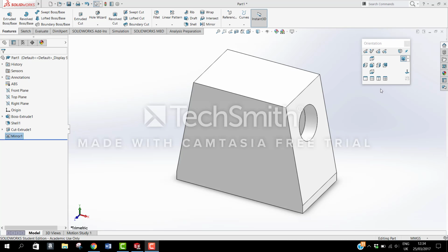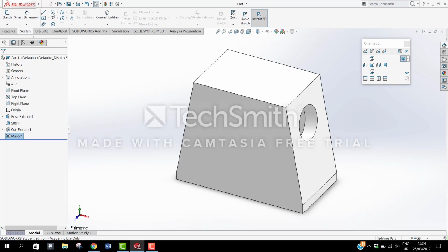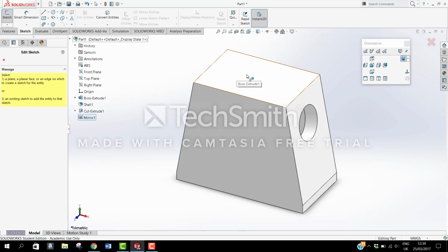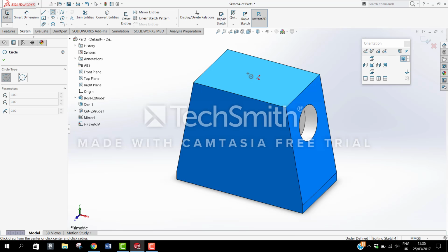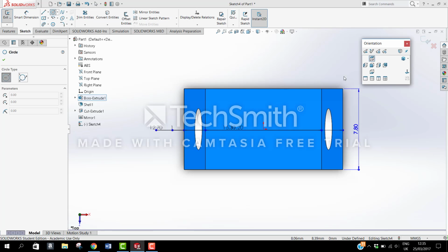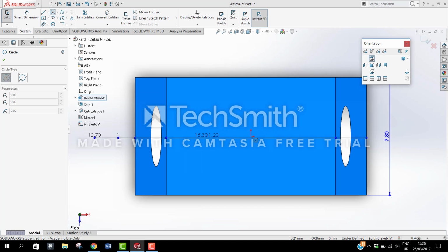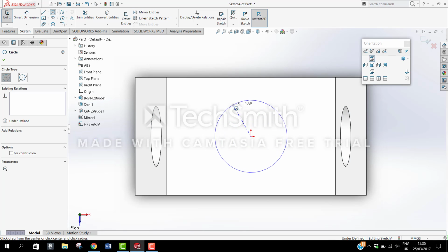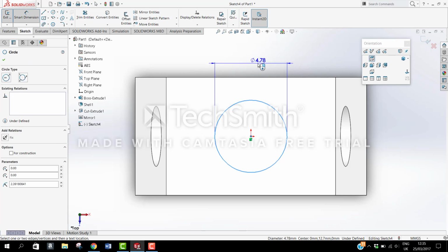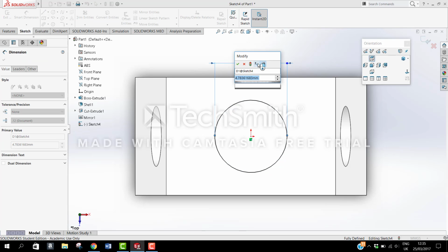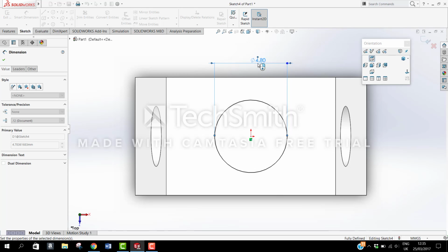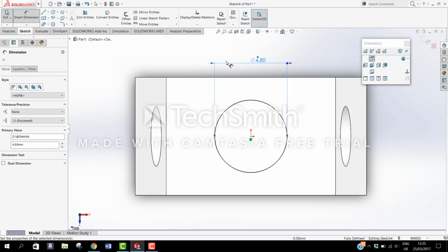So next we're going to do our circular extrude on the top surface. We'll start with a sketch, use a circle for the sketch and select a plane. We'll draw on the top surface and go normal to this, to make things handier. So just draw my circle at the moment, and I can dimension it to 4.8 in this case. And our sketch geometry is black again because it is related to the origin and it has been dimensioned,